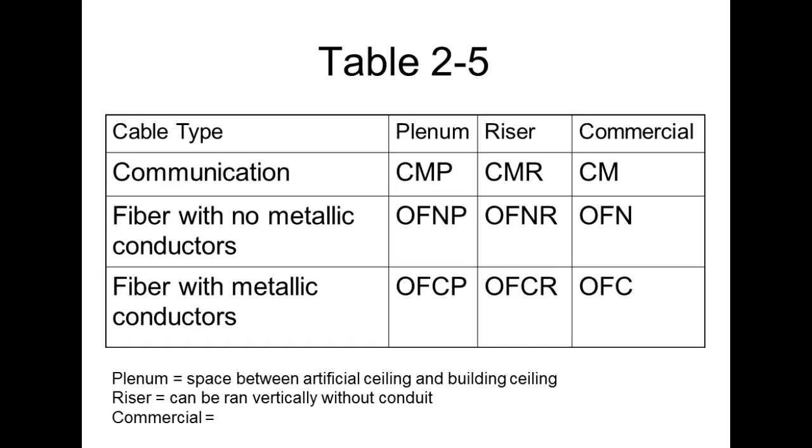Now, this is not the conductor. This is the cable, right? So this information is going to be printed on the what? On the jacket. If it's an insulator, what they're going to print on there is the temperature that it's rated at, and the voltage that it's designed to hold. That's required on the insulator. If it's a combination, then they put a lot of information on an insulator that also serves as a jacket.